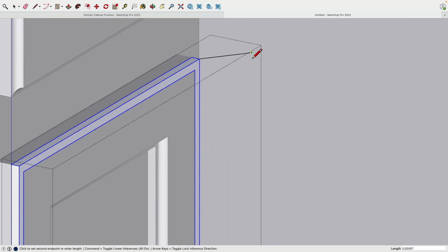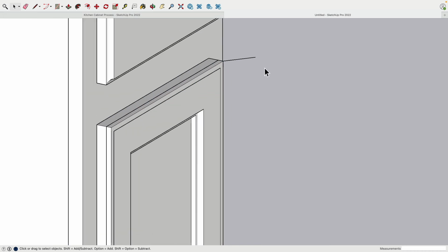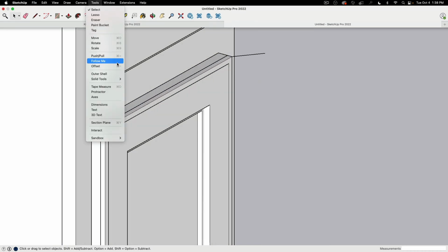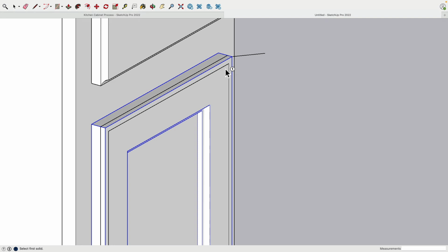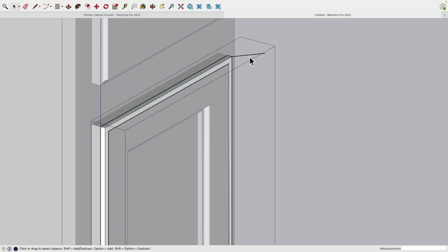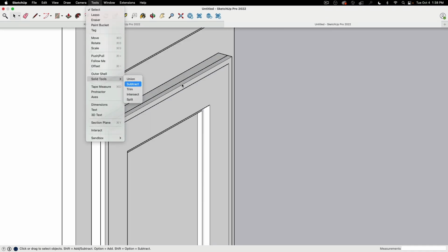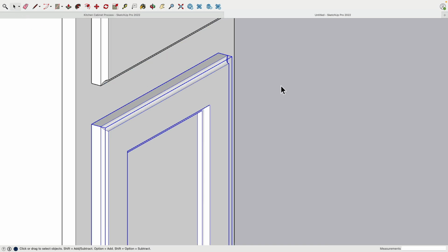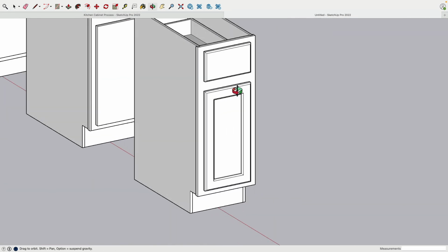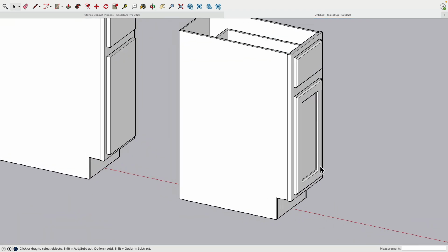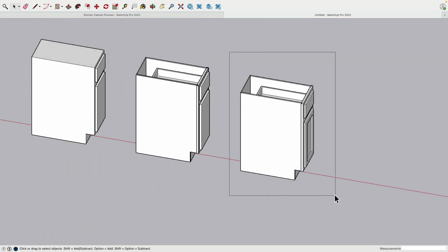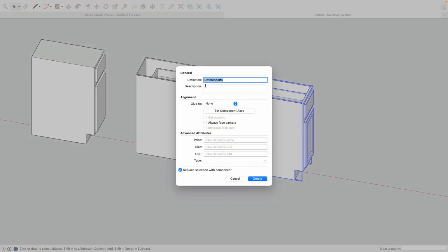I'm just simply drawing here a line. So this line has no volume, no? But this line already is enough for SketchUp to refuse using it. So when you try to do a solid command and something doesn't work, either you have somewhere a hole or you have these what's called naked edges. Just remove them. Then it should be all easy peasy. Very nice. Cool.